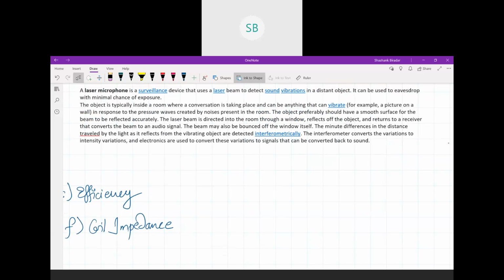Most MEMS microphones are a type of condenser microphone. There are digital MEMS microphones as well as some which have built-in analog to digital converters. They have a very precise size and precise sensitivity, so that you can use them for a special purpose by using these MEMS microphones.